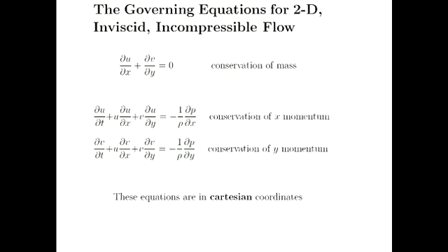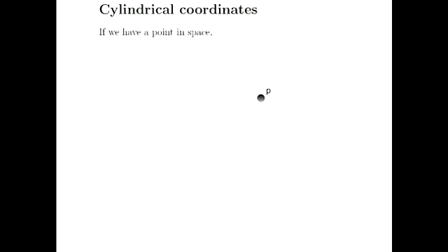Okay, so anyway, we've got that simplified set of equations. We got there from pruning down the Navier-Stokes. We could have just as easily derived them with some simplifying assumptions from that control volume analysis. At the moment, that set of equations is in Cartesian coordinates. We're also going to require that same set of equations in cylindrical polar coordinates. Believe it or not, it's going to make life easier for us at certain points through this course. So you've all come across cylindrical polar coordinates in other courses.